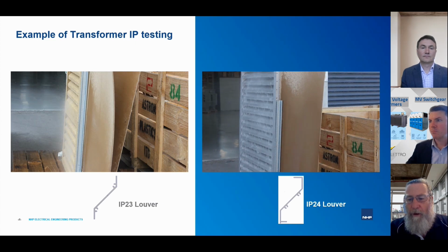Because we were changing the louver profile, we redesigned the transformer to basically give another 5 degrees less in the design top oil and winding temperature rise. It just happened to coincide with me going to Europe. So I hop on a plane, get to Singapore, and get an email to say they tested the transformer and we were 7 degrees below what we had delivered for West Wind. So I go, cool, extra 2 degrees up my sleeve.